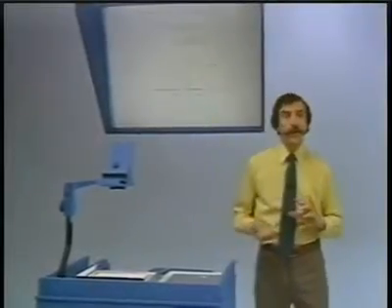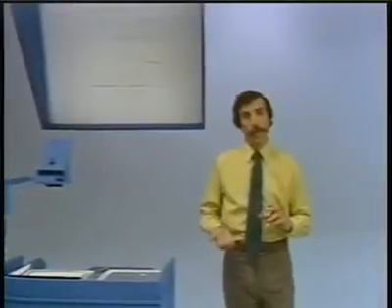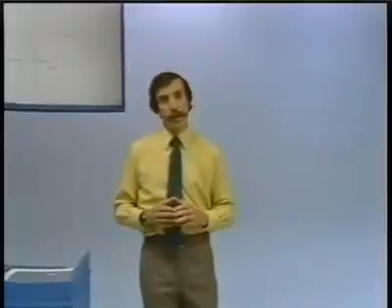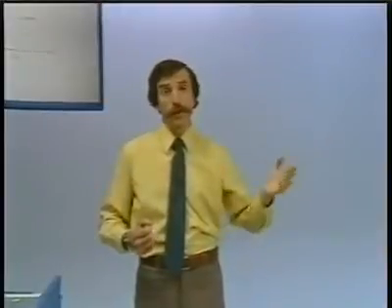So what we found is that with proportional feedback, we can't stabilize the system. With derivative feedback, we can't stabilize the system by themselves. And a logical next choice is to see if we can stabilize the system by both measuring the angle and at the same time being careful to be responsive to how fast that angle is changing, so that if it's changing too fast, we can move the cart or our hand under the inverted pendulum more quickly.